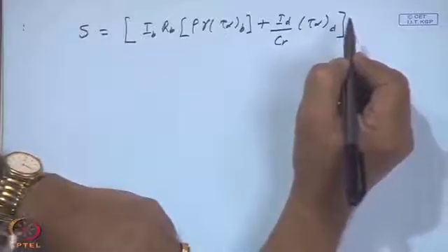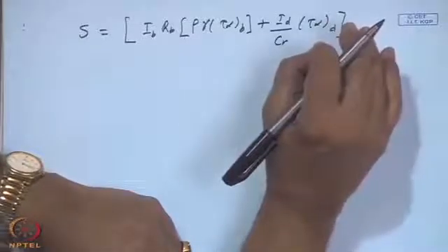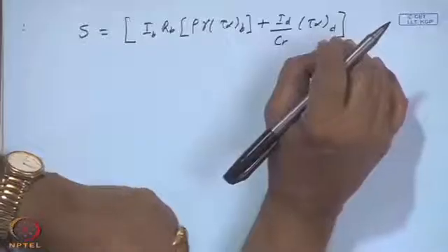So, we expressed basically the clarification regarding the concentration ratio for a circular concentrator and the linear concentrator, and subsequently I have also included the derivation of the outlet temperature of the fluid passing through the receiver tube of a concentrating collector, which is necessary to evaluate the heat removal factor and the flow factor.